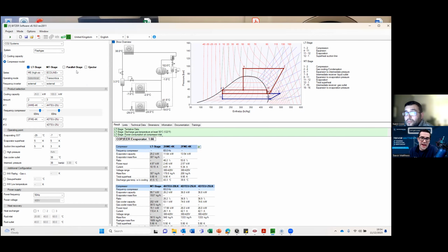You don't have to put all that flash gas coming from the fluid from the gas cooler when you're in transcritical through the high pressure valve, instead of going through the flash gas bypass valve into the medium temp suction, now you're going into a different suction at a higher pressure, reduced compression ratio, and increasing the efficiency of the system when designed properly. This can lead to smaller compressors as well. What are your thoughts on parallel compression, Nabil?